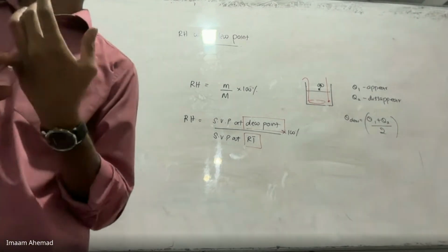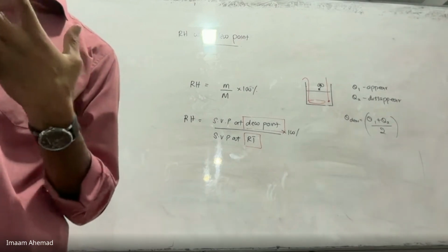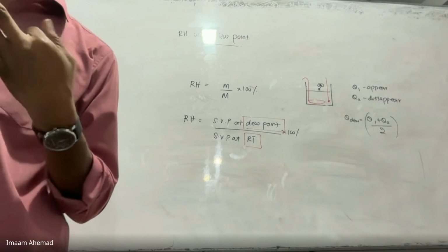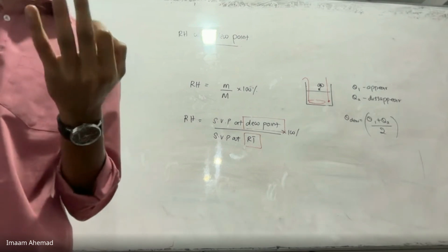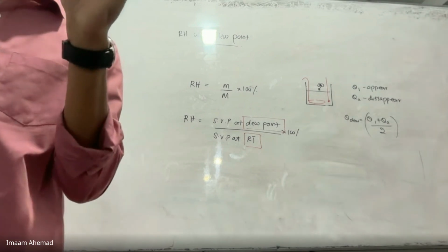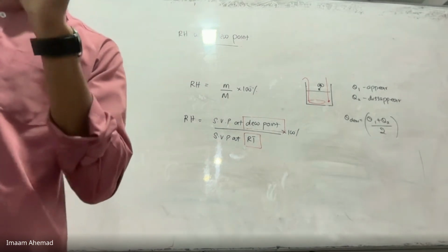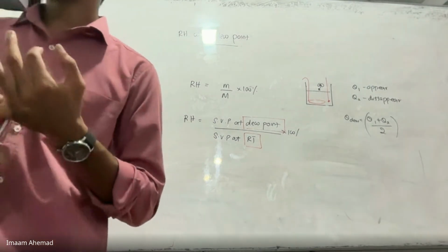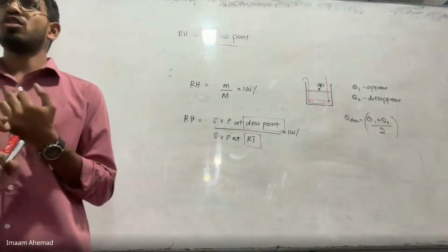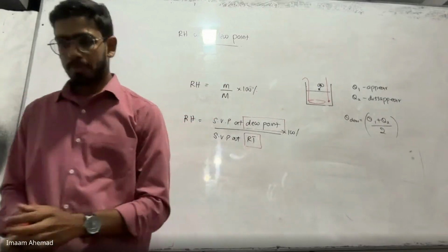Here, are we worried about heat loss? Conduction, convection, radiation, are we worried about this? Minimizing it is not necessary. This doesn't matter. We just want to find out the dew point temperature. So the main purpose of using a polished calorimeter is to clearly observe dew formation.